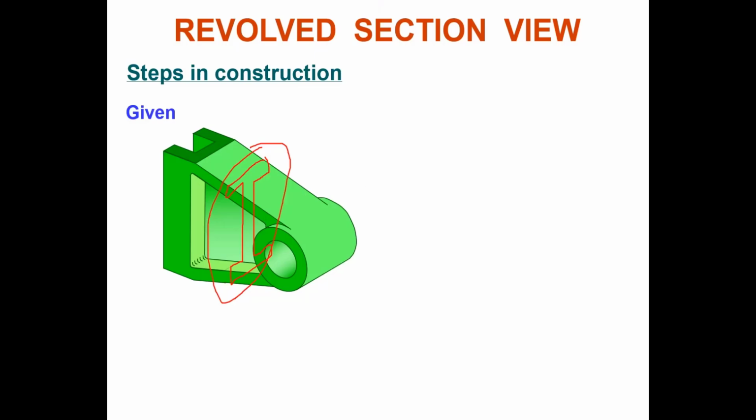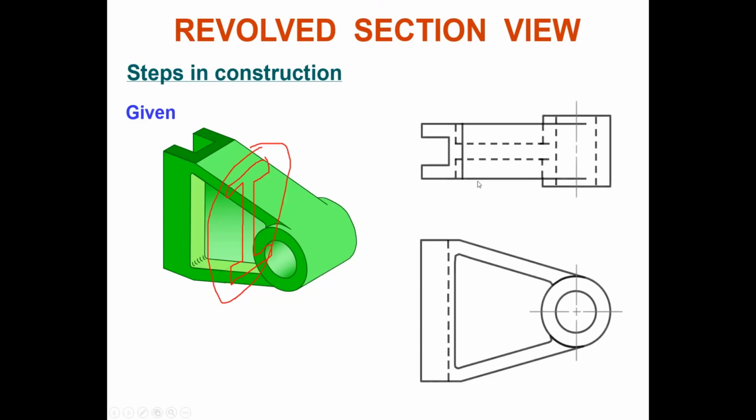Okay, for example, then you do your drawing. You do this typical orthographic. Front view, and above, the top one is your plan view. Now, if you do this typical orthographic drawing, it's not following the standard. So that's the idea of this sectioning. This is what we call revolve section. If you make a full section, hold on, let me erase this.